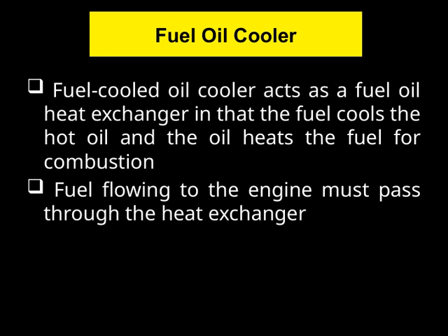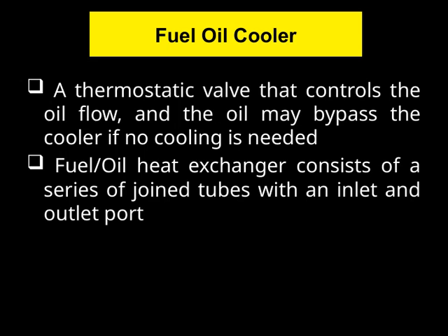On this slide, we see a thermostatic valve that plays a crucial role in controlling the oil flow within the system. What's interesting about this valve is that it can adjust the flow based on the system's cooling needs. If the oil doesn't require cooling, the valve allows the oil to bypass the cooler entirely, which helps maintain efficiency and prevents unnecessary cooling.